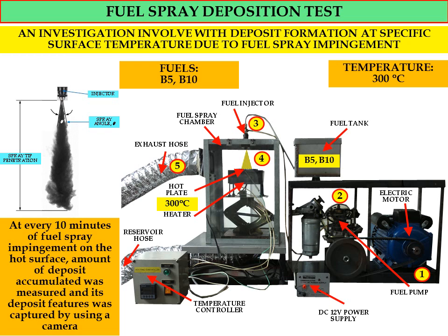So in this experiment, at every 10 minutes of fuel spray impingement on the hot surface, the amount of deposit accumulated was measured, and its deposit features were captured by using a camera. So these are the basic process of the fuel spray deposition test.